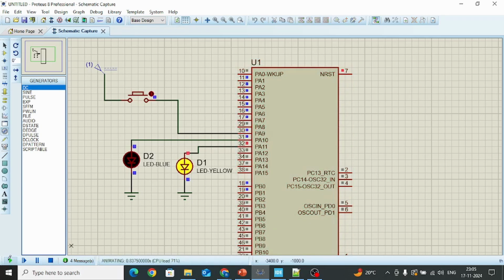So you can see this yellow LED blinking. So you are reading the book. Now your friend will come. Now the friend comes and rings the doorbell. Upon pressing the button, nothing will happen because our interrupt will trigger on the falling edge. Now when I release the button, you can see the edge falls and the interrupt is called. Upon the interrupt call, the processor executes this subroutine. It simply toggles this LED. Now the LED is on.